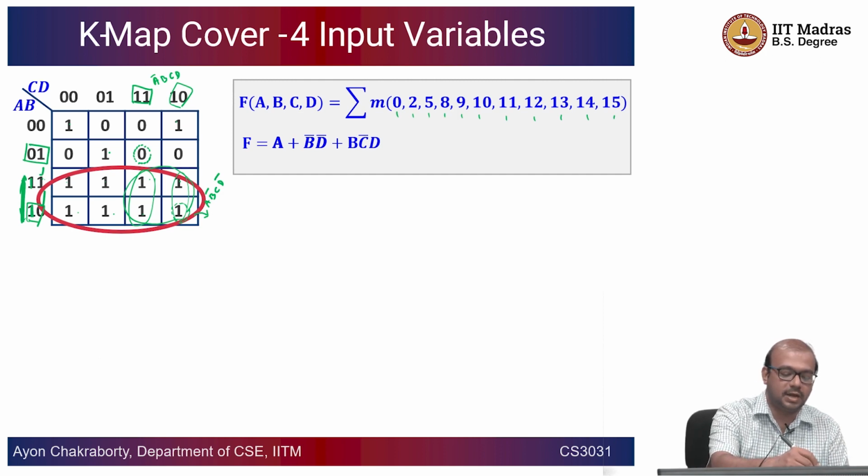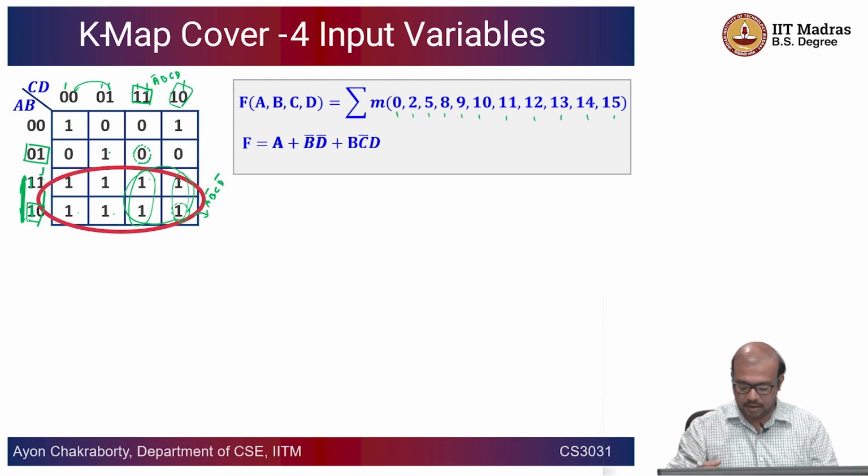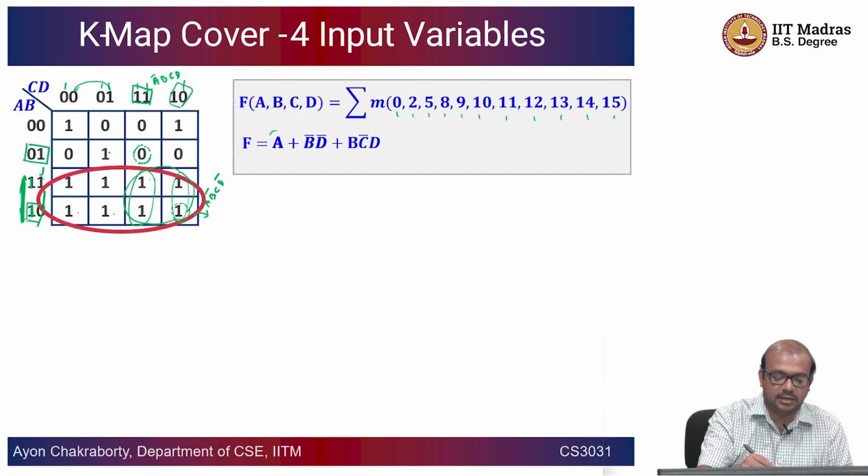If you look at this, it has all the different min terms. It has C bar D bar, and this is your C bar D, so this is going to cancel out D. Similarly, you had C here and this is D plus D bar, so this also gets cancelled out. It becomes C plus C bar, and that also does not matter, C plus C bar becomes 1. So ultimately you are left with only A. That is how you got A.